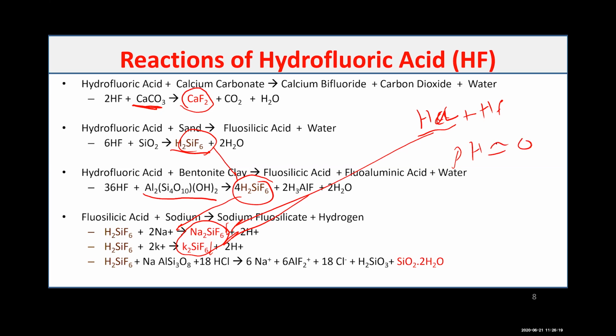It starts to precipitate when the pH becomes greater than 2. So the reason we always have HCl with HF is that HF is the acid that does the dissolving, the one that does the work and removes the silica. However, the reason we have HCl is to be sure we are keeping the pH at 0.